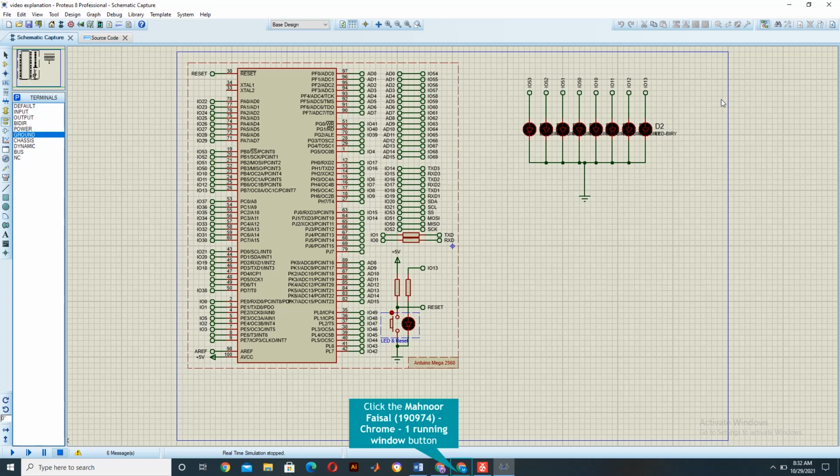It is written as 50, 51, 52, 53. So with these labels the pin configuration becomes much easier. You just find 50 and go there, and 50 is PB0. That is why having these PB labels makes it very easy to identify which value it is.